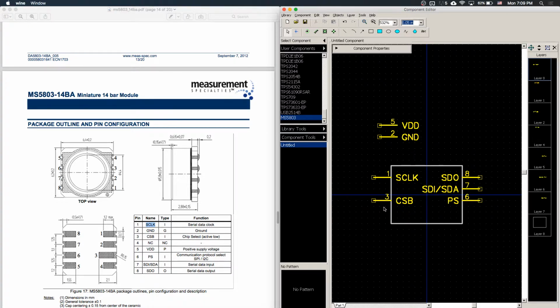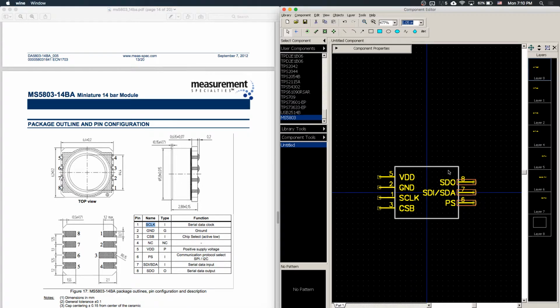So you can group the pins together rather than follow the U-shape pinout of the chip, but just make sure the actual pin number of each pin matches exactly what you expect on the data sheet. So this will be equally valid as a component.